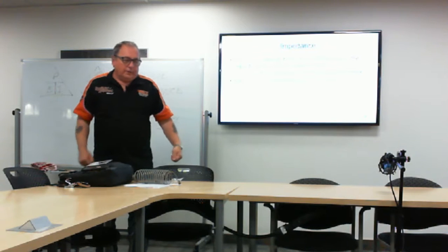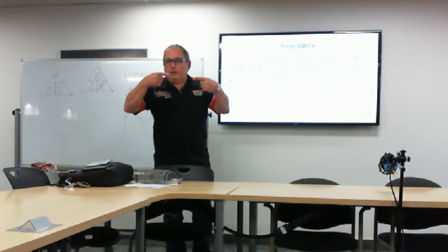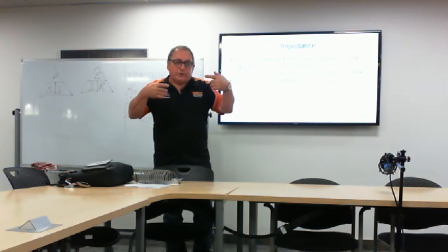If we put an inductor and a capacitor in series, now we have inductive reactance and capacitive reactance. Something's going to happen, right? The thing that can happen is that we can get to a point where it looks like there's nothing there. That's called resonance. Because one is slowing the current, one is speeding the current, so they're going to equal out. They neutralize each other.